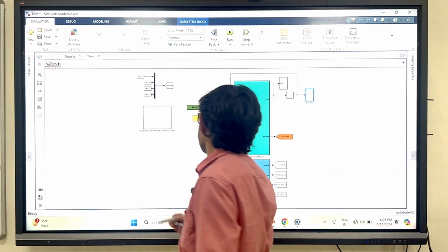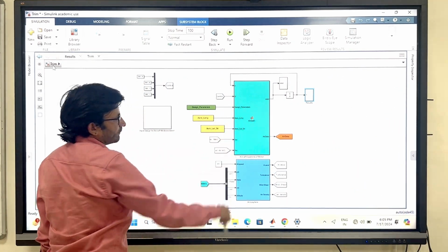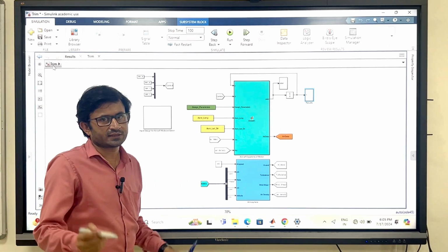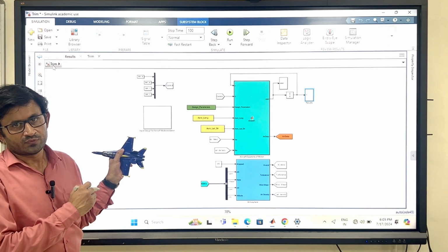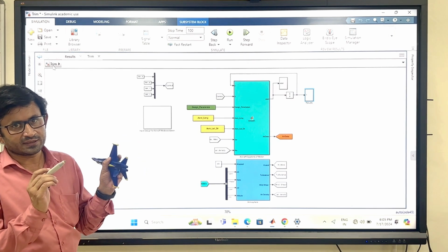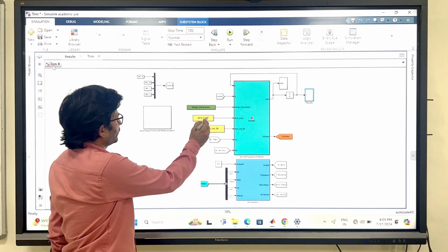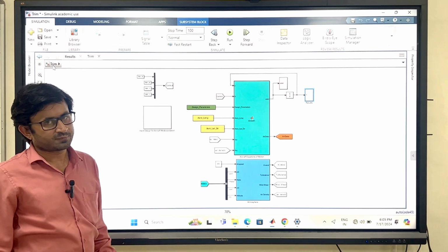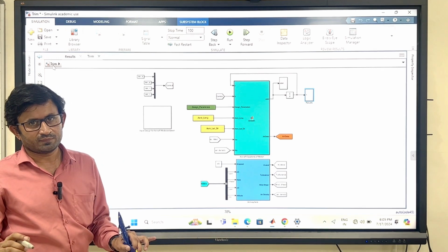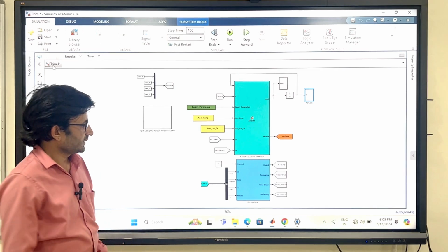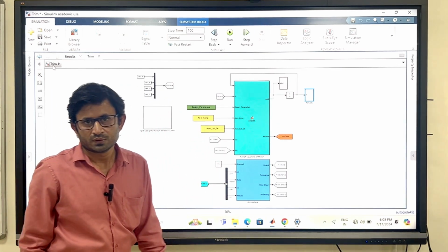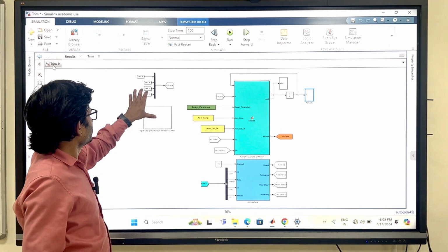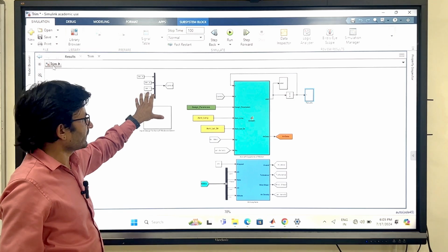You can see here I have written my equations of motion in this block. This block requires aerodynamic data; in the last class we constructed the flight aerodynamic model. Longitudinal, rudder, design parameters, everything you have to enter. The atmospheric model we have also done, right? That also you have to provide: what altitude, what condition you are flying. The initial controls at trim you have to supply.